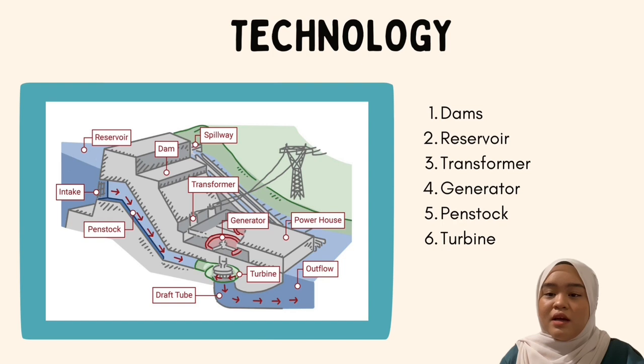On the other hand, reaction turbines are suited for low-head applications. These include Francis turbines, commonly used in medium-head settings, and Kaplan turbines, utilized in low-head settings, featuring adjustable blades and enhanced efficiency. The primary function of both turbine types is to convert the kinetic and potential energy of water to mechanical energy through the rotation of turbine blades.